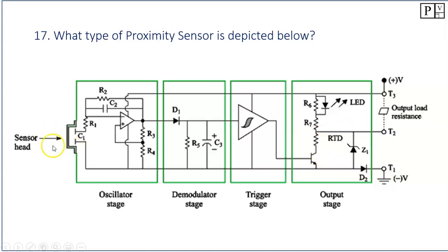What type of sensor is it? Well, we've got to look at the sensor face right here. And there's a C there, so this one is a capacitive sensor. Similar to the one where we had the coil for the inductive sensor, the two plates of the capacitor are normally on top of each other, but they have been opened up like a sandwich, and the inside, or the dielectric, is going to be air. Then if we put something in front of the sensor, it will change from a dielectric of air to plastic or metal or whatever we put in the front face here. So this is a capacitive sensor because we can see the two plates of the capacitor, and whatever is in the front here is going to be the dielectric.